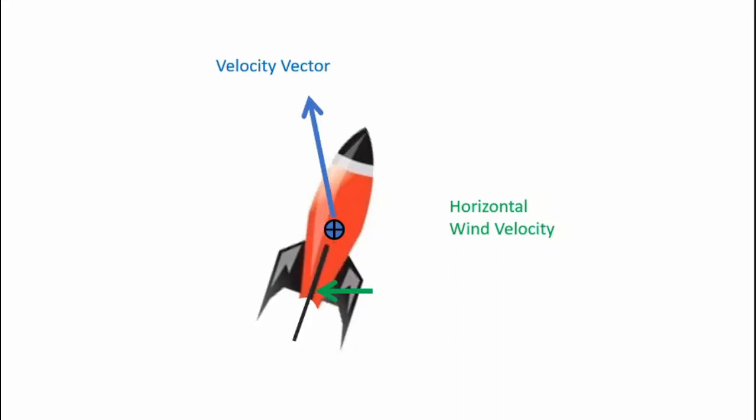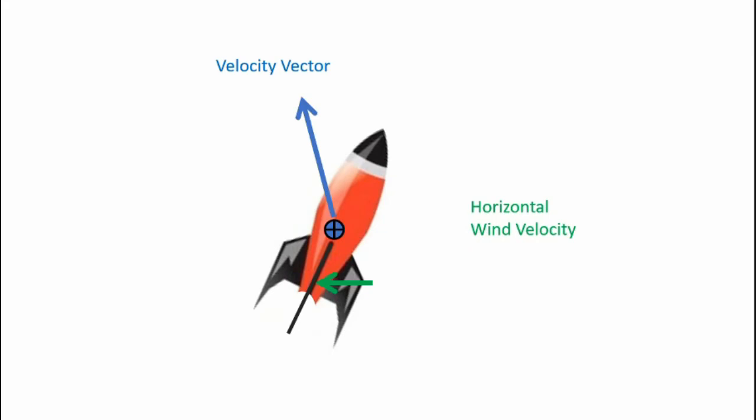Now let's focus just on the wind blowing on the fins. It causes the rocket to pitch into the wind. However, since it's not thrusting, it's not flying to the right, it's actually drifting more to the left. And the velocity vector tilts slightly more to the left. And as it stays in the wind profile, it pitches more, and the velocity vector changes ever so slightly to the left. Now, at some point, the rocket picks up the same velocity as the wind, so the velocity vector will not shift much.